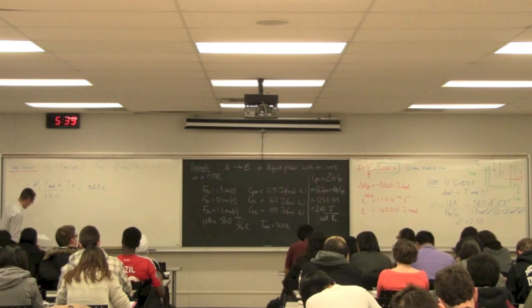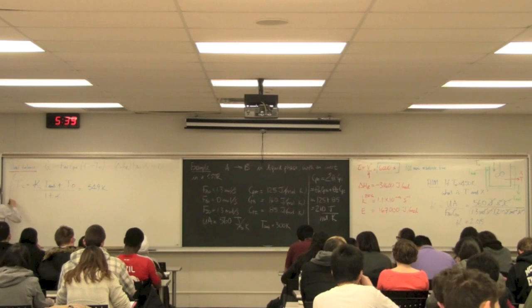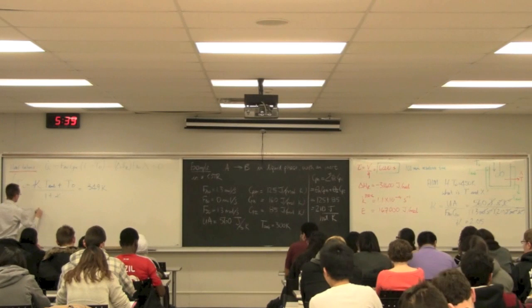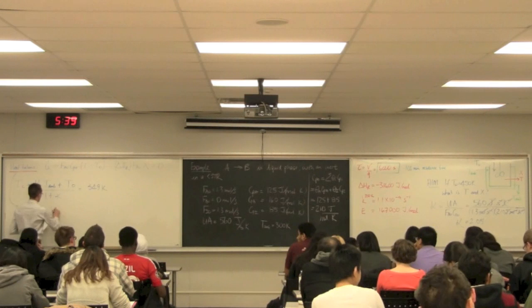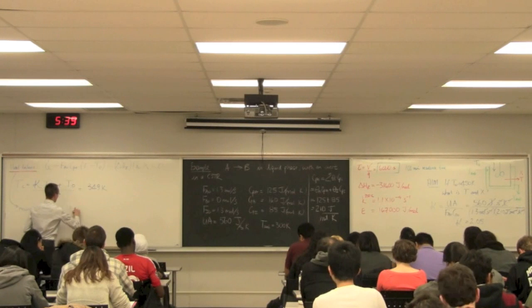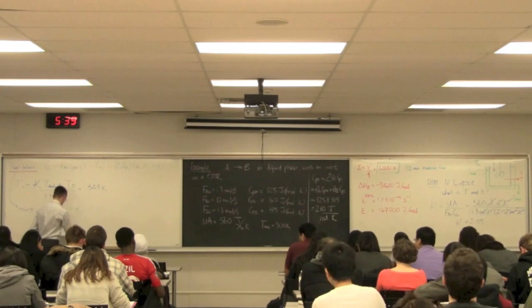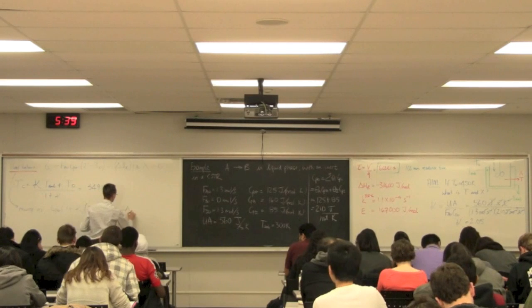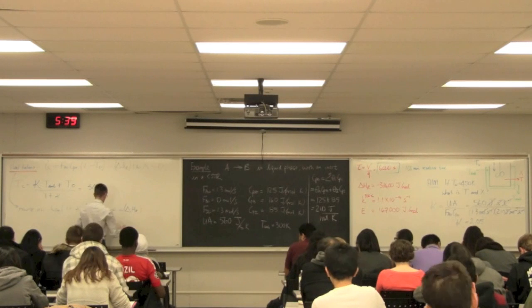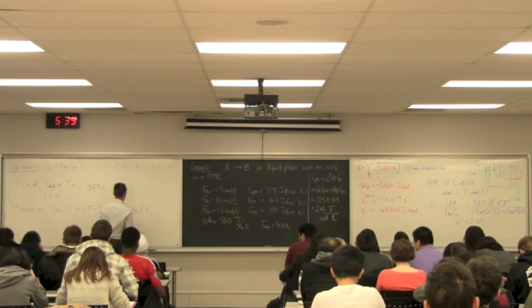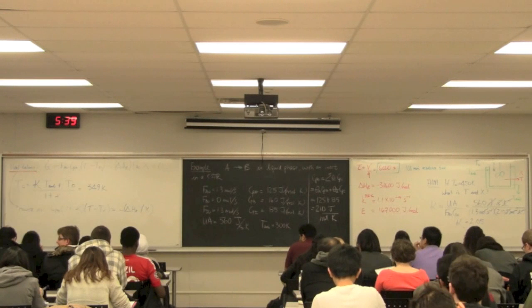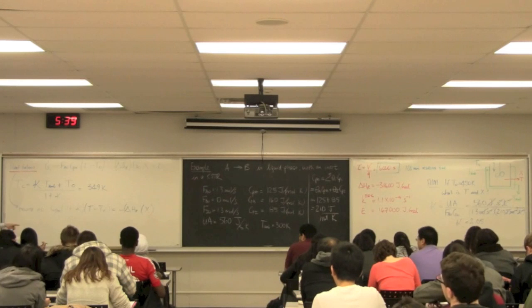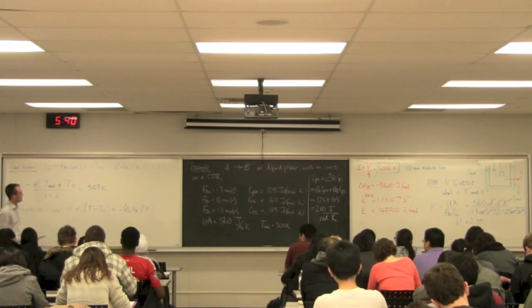So we can rewrite this, as shown in the previous class, as C_P0 (1 plus kappa)(T minus T_C), and that's going to equal the negative of the heat of reaction multiplied by conversion X. Okay, so you can prove to yourself that you can get to this point from this point up here.